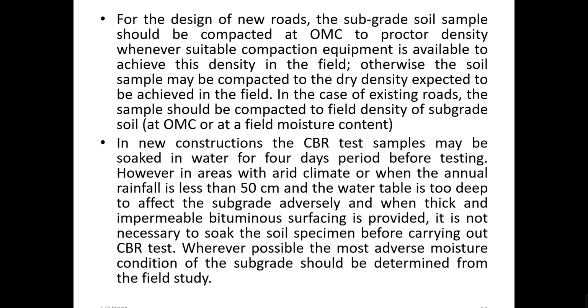It is because whatever test we conduct in the laboratory by mixing water into the soil, we note down at which optimum moisture content we obtain the maximum dry density. That quantity of water should be laid at the practical site to obtain the maximum dry density. That is why they lay the water at the practical site before the roller is rolled over the road surface. They moisten the soil.